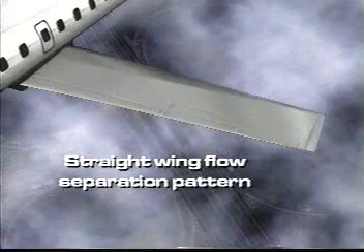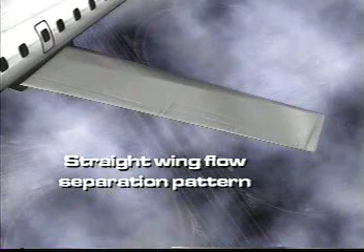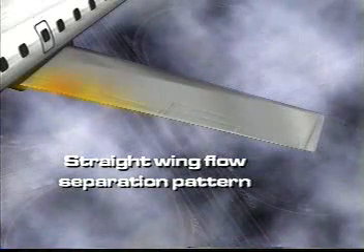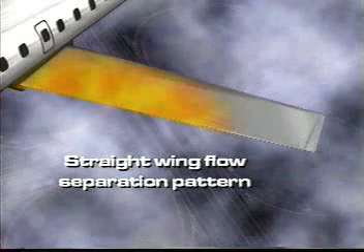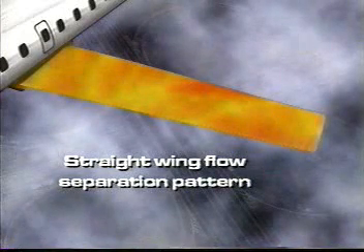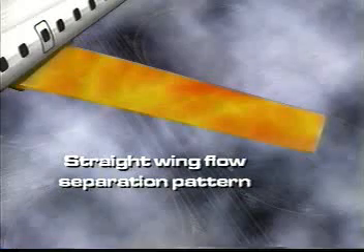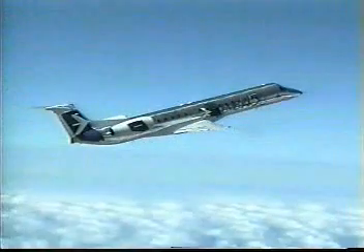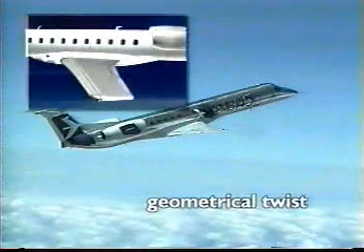The straight wing exhibits low lift at the tip and high lift at the root, which contributes a lot for favorable stall pattern characteristics, adequately signaled by the stall warning buffet, adequate aileron effectiveness, and the usual strong nose-down moment. There are several means of correcting the tip stall tendency.